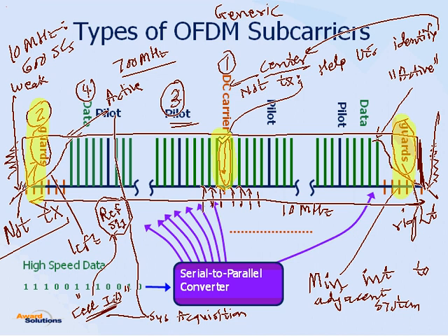Also, we will use the pilot signal to measure signals, and okay, so that is for handover or handoff measurements. So in 1X, DO, UMTS, we look at the pilot strength, Ec/Io. In UMTS, we call it Ec/No. Same way here, the UE will measure the pilot signal strength. And a little later, in a future session, we will see that we have so-called RSRP, RSRQ. Those are the pilot strength measurements. Okay. So that will tell us how good the channel conditions are.